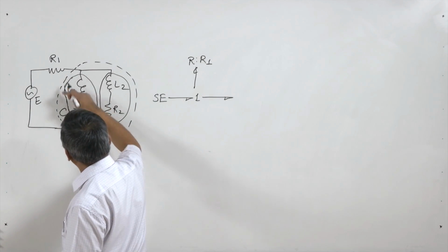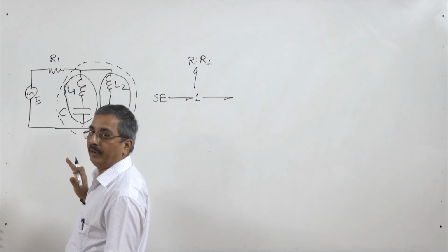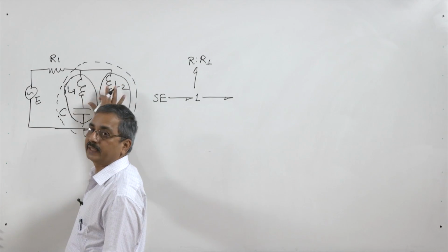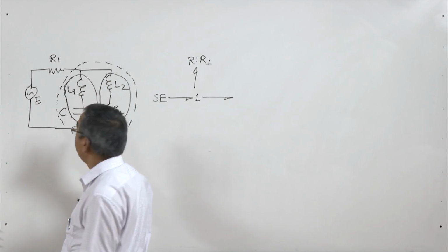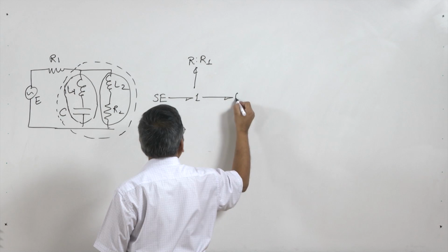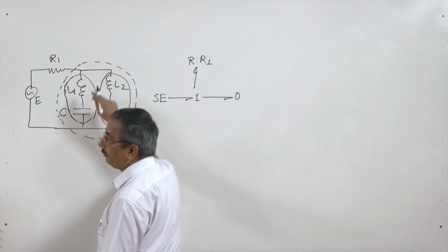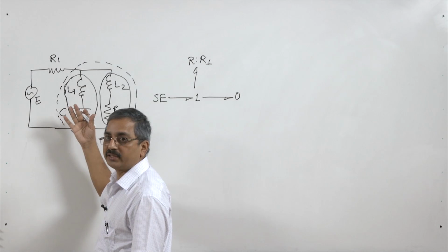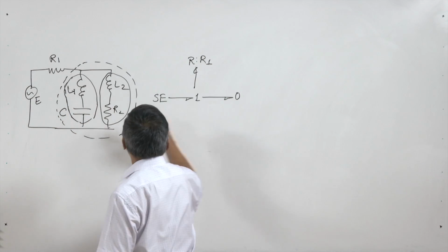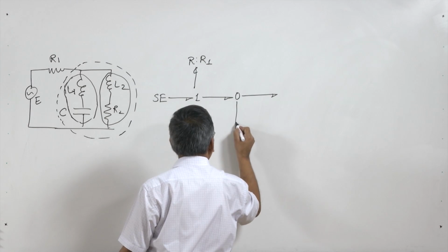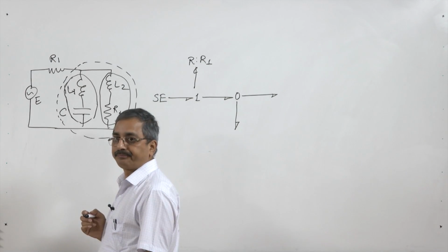So, if I take each as one element, then I say that these two envelopes are in parallel. Okay. So, what I do? I put a 0 junction, okay, because parallel means they have the same voltage or the same effort. Okay. So, the 0 junction here and here I put for these two.